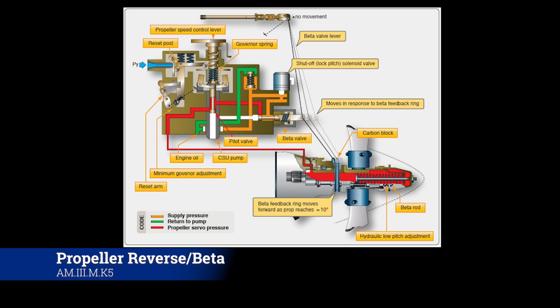All right. In the event of a propeller overspeed not controlled by the propeller overspeed governor, the flyweights in the propeller governor move outward so the speeder spring cup contacts the reset lever. The movement of the reset lever around its pivot points opens the Pi air passage. The Pi bleeds into the reduction gearbox, limiting the fuel supply to the engine. This prevents the propeller and power turbines from accelerating beyond 106% RPM. Now, that's a lot to basically say that once you're in beta mode,